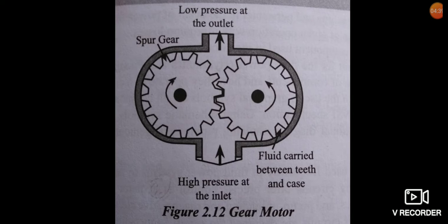Piston motors are either radial or axial and are available in the power range of 2 to 25 HP. Maximum speed is around 5000 RPM. The axial motor has axial pistons which act on a swash plate and produce rotary motion just as an axial piston hydraulic motor. The key to the radial piston motor is valving, which directs compressed air into the correct piston. The radial pistons act on the cam in sequence to produce rotary motion.